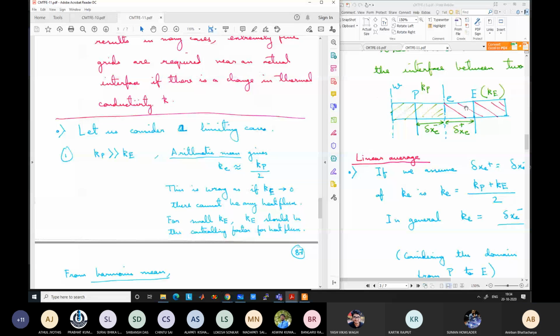You are able to hold that wooden spoon. Similarly, you are able to hold the handle of the pressure cooker, although the pressure cooker is at more than 100 degrees centigrade, right? Because you have an insulating material on the handle of the pressure cooker. So the heat flux will be almost zero, a very small amount.